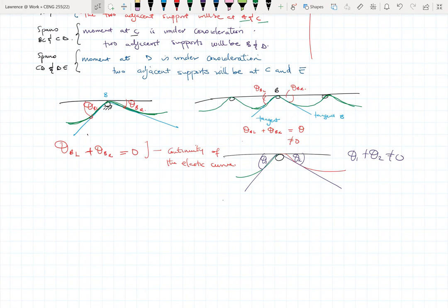For example, if you are building a house, the carpenter that does the formwork, if the wood that is used for the formwork is not straight, there'll be variations in your beam sizes.